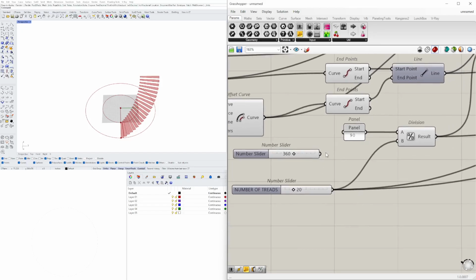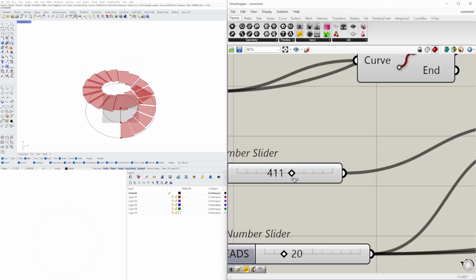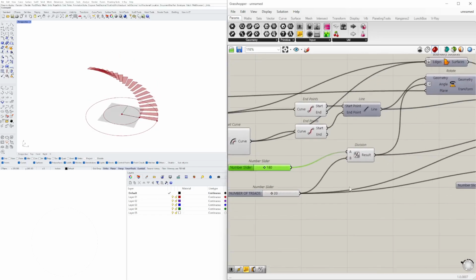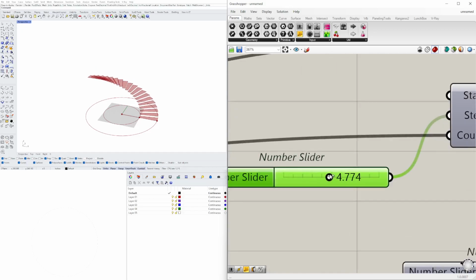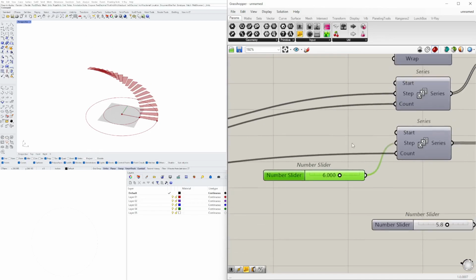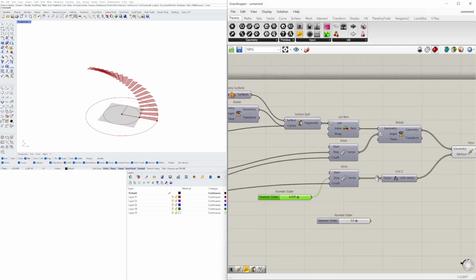This way we can change this to be from 360. It could even go more, or it can go less. 360 is typically the normal one, but we can also do 180, which means it just goes, let's say, from here up to the second floor. Tread height, by code, 6 inches for commercial, and then you can go up to 7 inches if more, or 7 inches and more if you're in residential.